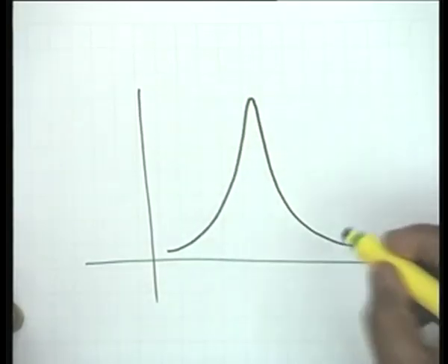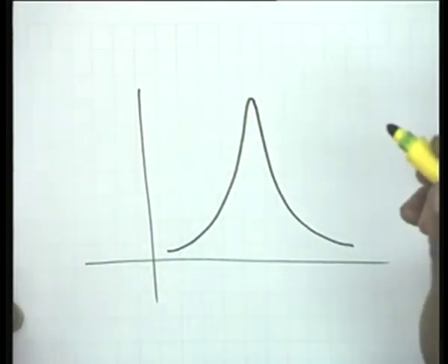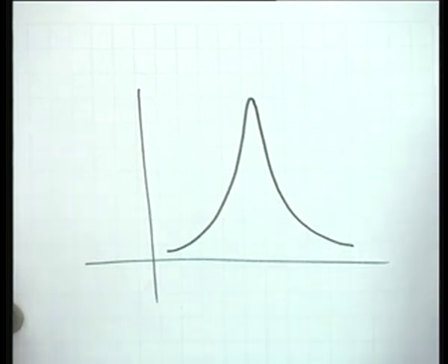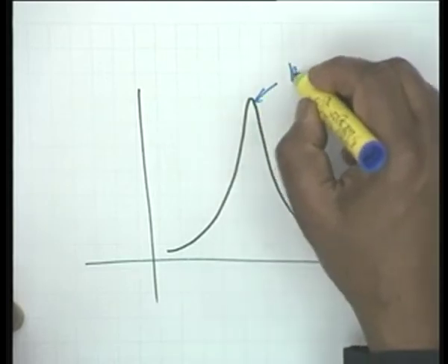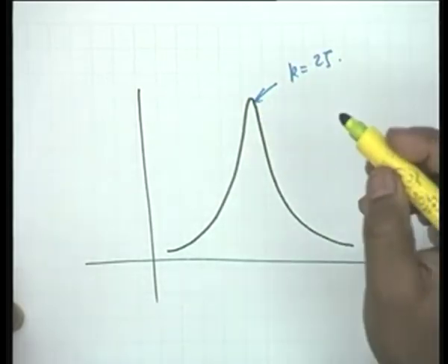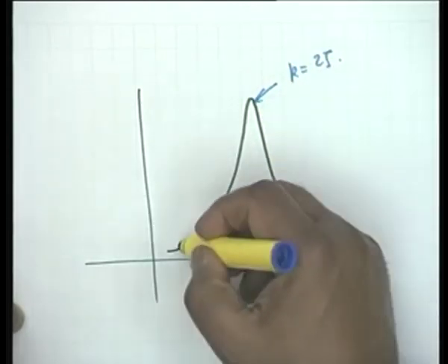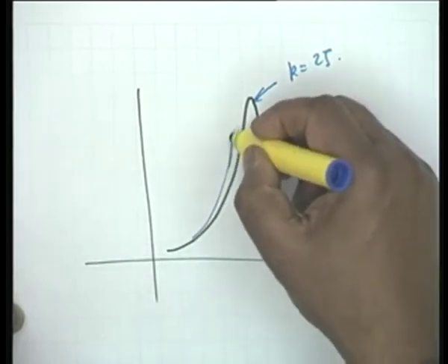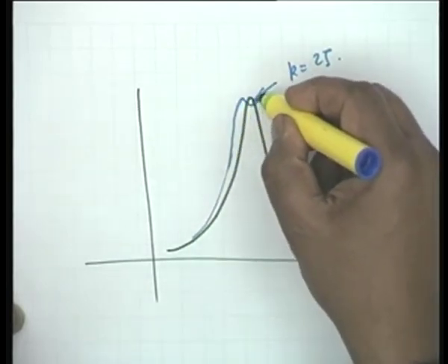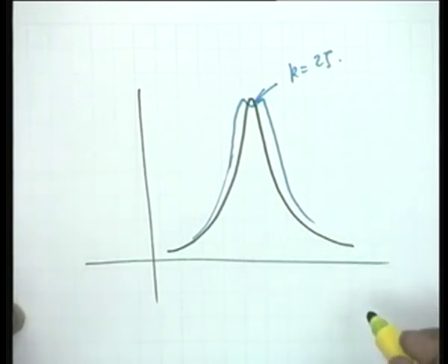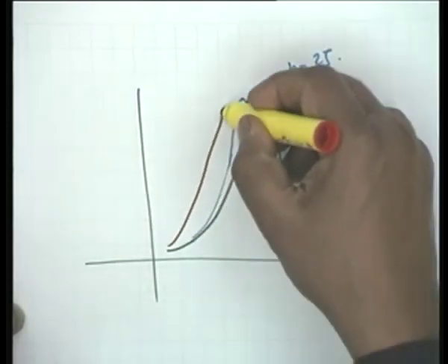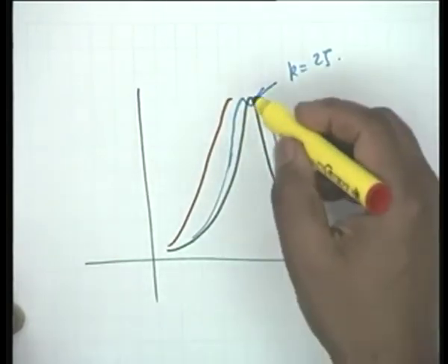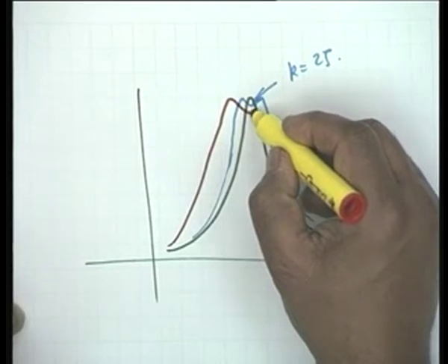This is the case when critically coupled, k equal to 2 zeta. When k becomes slightly greater than 2 zeta, well, maybe the curve goes like this. When k goes higher than this value, the blue curve, perhaps it goes like this. Maxima are the same, but the dip is higher.